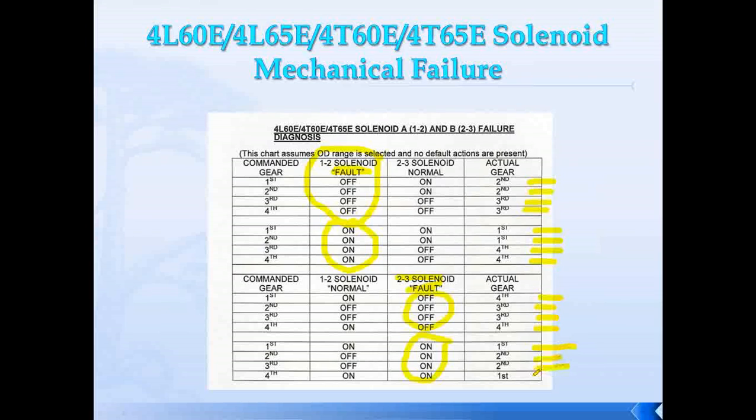And now what happens, because this has happened several times to people and they get confused by this, is that if you can get going high enough road speed, the transmission is going to make a shift back into first gear again when it's supposed to be going to fourth. What it boils down to is that you do not have enough engine to run this vehicle down the road in first gear at highway speeds. So the vehicle acts like it's going to neutral on you.